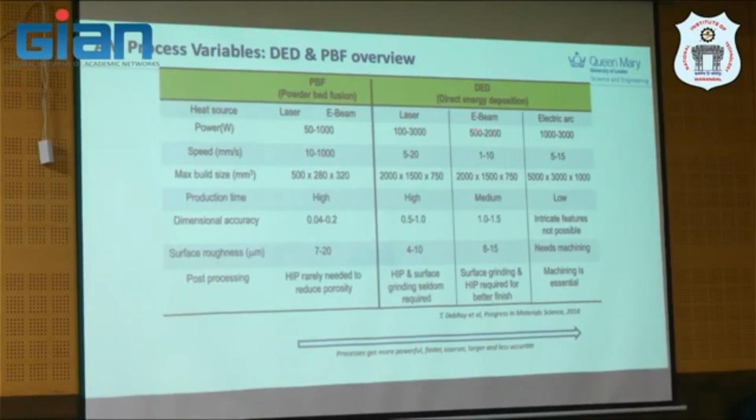And also, if you want a very high production rate, it's actually PBF, because you see this one is small, but this is high. But if you want a larger build, you need to use DED. Again, this is a compromise because you won't get the resolution you want. The resolution is relatively low or medium, not very high, based on the characteristic of the process and the feedstock resolution. This also contributes to roughness, but some applications require roughness.